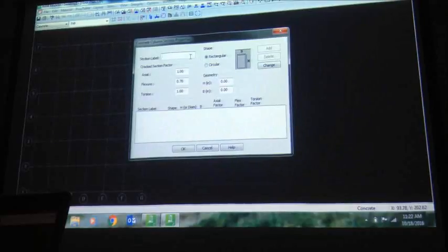In prop table, you can say I need my column. You can define column sections and beam sections. So let's give a column section and a beam section before we move on to the laying out of the beams and columns. Okay, is that okay? So column sections, it says C means column.